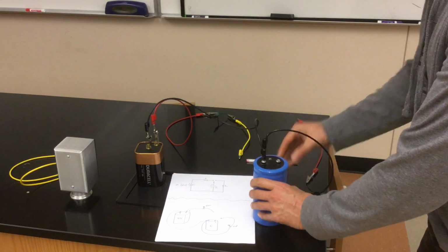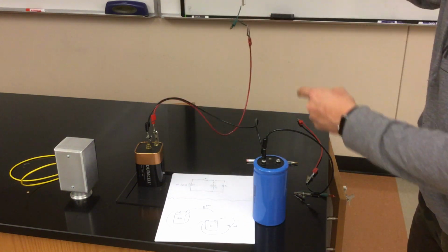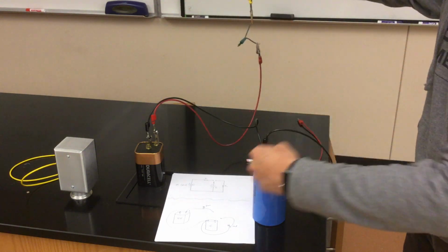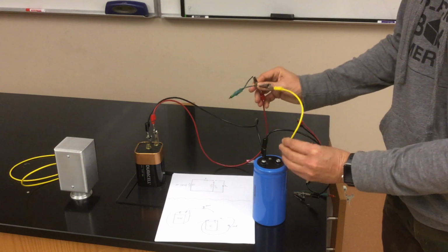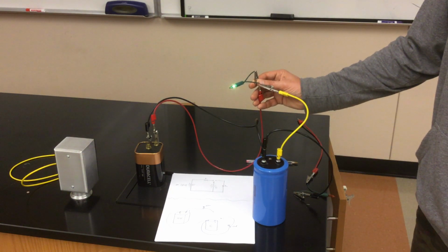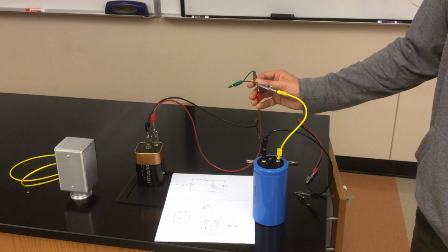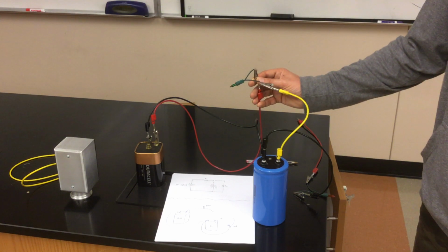And then let's complete this circuit from the battery to the light bulb through the capacitor. We say all 3 elements are connected in series. And what we should see is the light bulb glows brightest at first, but then eventually fades out and goes dim and isn't glowing at all anymore. Why is that?